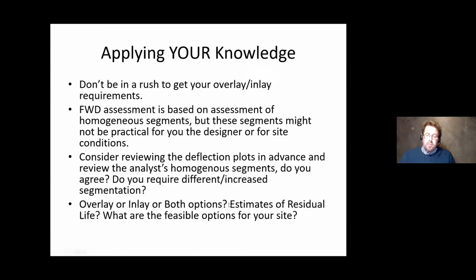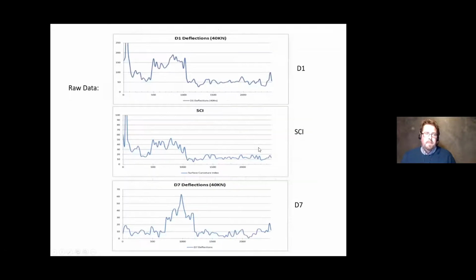Likewise, most FWD operators can also give you an estimate of the residual life of the pavement, and this can tell you how much life you have if you do nothing. That can be a handy thing to keep in your back pocket: if the costs you're coming back with for an overlay or inlay for your 10-year design life are exceptional, well, if you do nothing, this is what you're getting. And likewise, you can ask them to do, say, a 5-year example. Don't be afraid to vary your design lives.